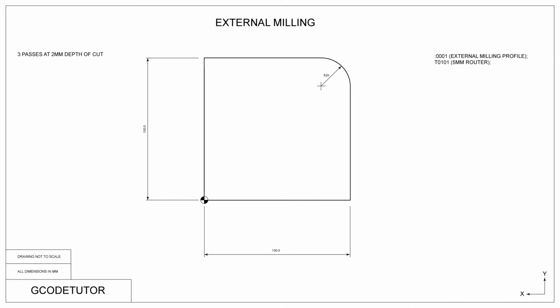Moving down to our next line, we designate the tool number. The T01 says tool number 1. The second 01 is the offset number, so here we have tool 1 offset 1. We complete this line with a bracketed comment. This is so the operator knows what tool 1 is at an easy glance.